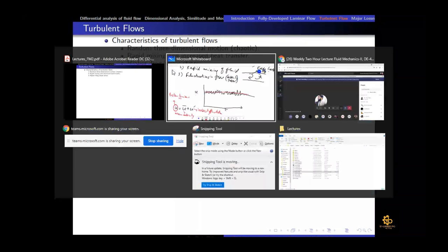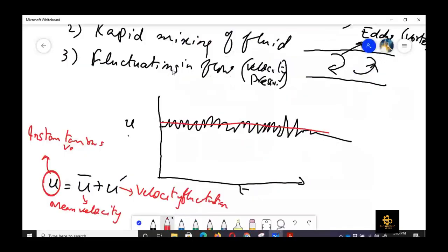Okay, the last thing which I forgot to mention is higher drag, or shear force. That is also the result of these eddies. Normally the velocity in the near wall region is very low, but if a vortex brings very high velocity fluid near the wall, du/dy increases, because we know that tau_w = mu du/dy at r = R, the pipe surface.